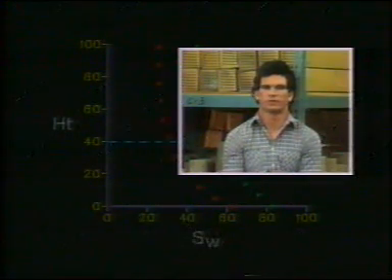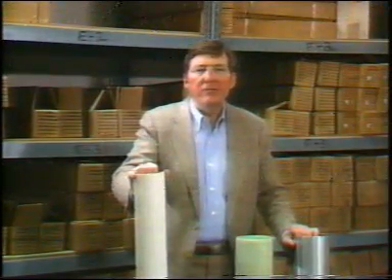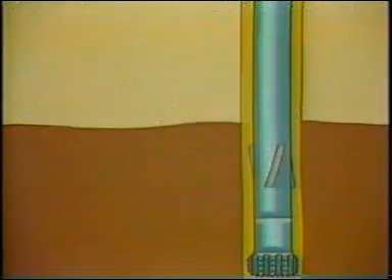To determine residual oil saturation and preserve wettability, we use a bland water-based mud with no surfactants, a pH of 8.5 or less, and an API filter loss of 3 to 5 cc's. For residual water saturation, we use an oil-based mud with physical properties close to oil, low surfactants, and low API filter loss.